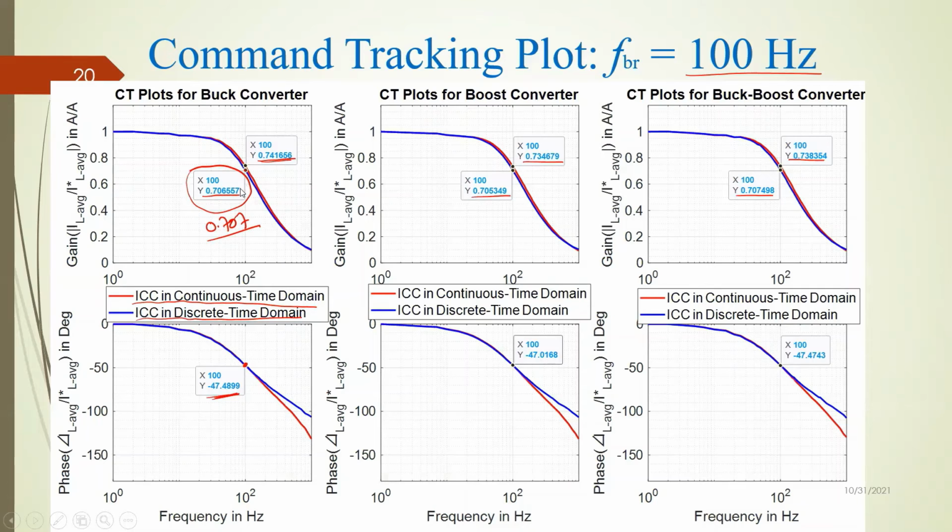So we have these variations because the switches in the system are working in a discrete time domain. The switches in DC-DC converters are not like a continuous voltage source signal, so we get switched voltage signals. This PWM implementation makes our system more discrete time domain, and so using a continuous time implementation, we would have some errors for sure.